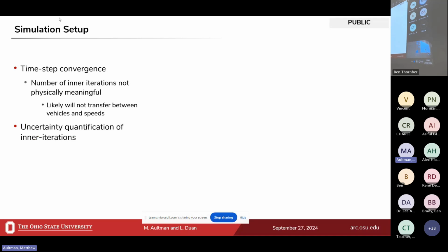If you consider the drag coefficient and the last 2 iterations for a given time step, there's kind of a question here. What happens if for one time step, the difference between those iterations is, say, 2 counts, and then at the next time step, it's half a count? How does that uncertainty start to impact your transient solution and the subsequent statistics?